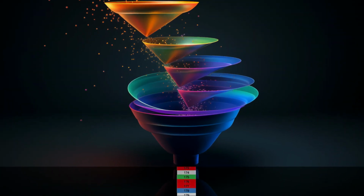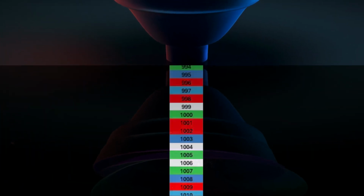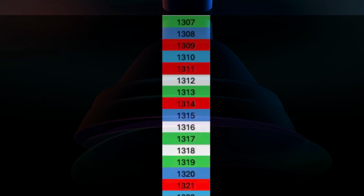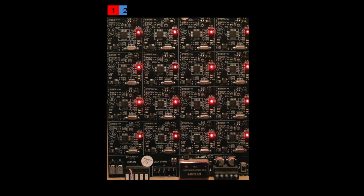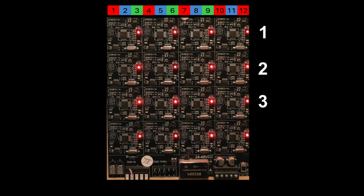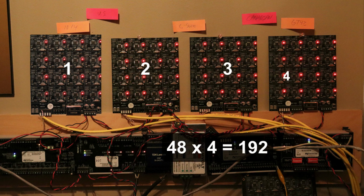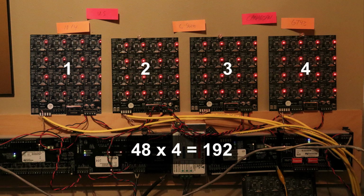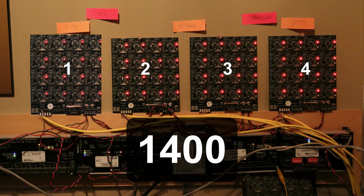Now, to make all of these pretty colors at the falls, there's a lot of data coming. And DMX comes at 40 hertz, and there's 1,400 channels. And on our lambda tiles, I only have red, green, blue, red, green, blue, red, green, blue, red, green, blue across the top. That's 12, and I've got 4 rows of that. So times 12 is 48 DMX slots, and I have 1, 2, 3, 4 tiles. So I only have 192 DMX slots to represent 1,400.